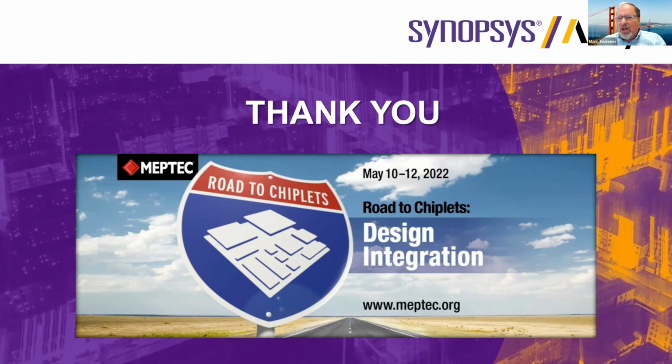If I have 2 or 3 blocks and I put them next to each other and this is the RTL roughly activity, what's the temperature going to look like more or less? And you want to avoid putting hotspots right next to each other or God forbid on top of each other. Because if you do that, you get through all your physical design and finally you do the sign off and find out this design could never have worked. It was just thermally limited.